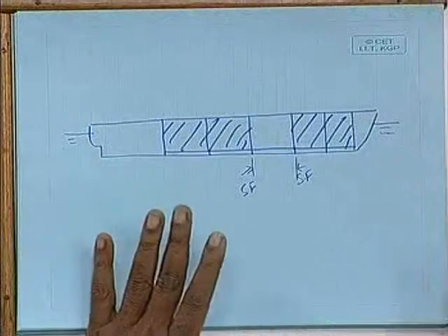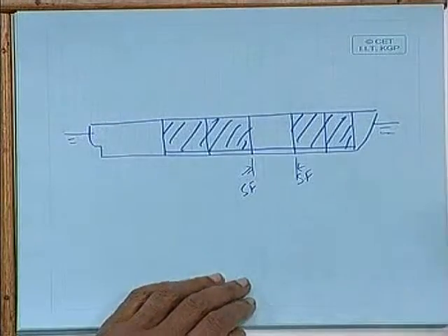And then what is going to happen to the shear force and bending moment curve? You can see here that the shear force will be maximum at these locations. The shear force will become high here. Can you understand that? And therefore, there will be a change in bending moment. So, even the static bending moment, which forms the core of ship hull girder strength calculation, has a lot of uncertainties coming up with it, depending on various factors which are normally associated with ship operation.